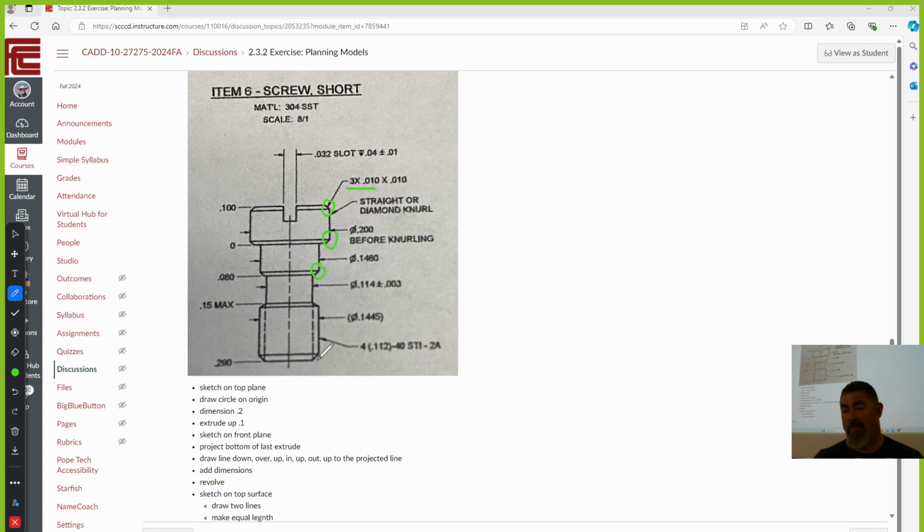Yeah, that's where the thread thing is. So, anyone know what those should be? These aren't called out. Do you remember what our note said on our title block about threads? No, where's the title block? Give me back to the title block. Remember back a couple weeks? Remember there was a note in the title block notes. It said chamfer all threads.